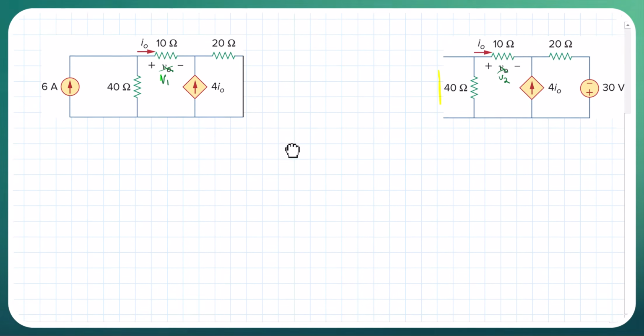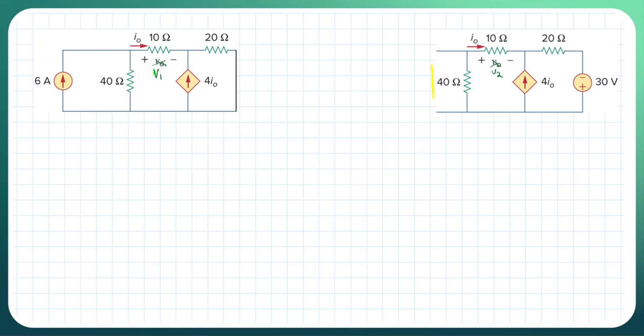So we're going to come down here, and let me define this point as node VA, this point as node VB, and I'm going to define my common ground here. As I do that, of course, I have current. I'm going to say I have a current coming in here, and we have I naught going out there. I'm going to call the current coming down this way I1. We have this current going up, and then I'm going to define my current going in this direction as I2.